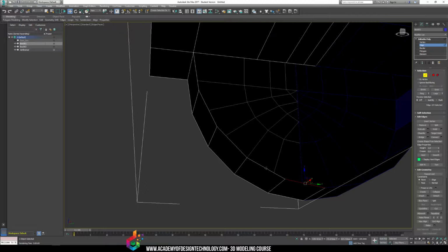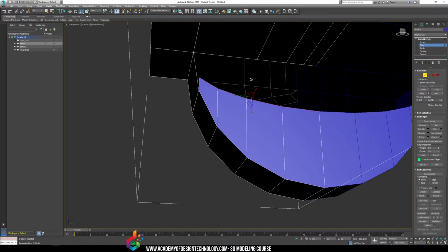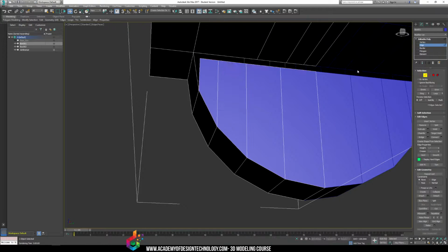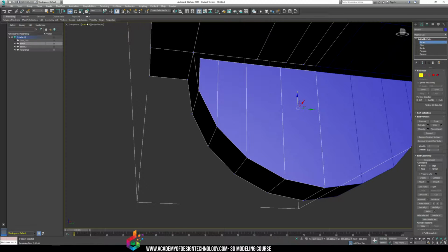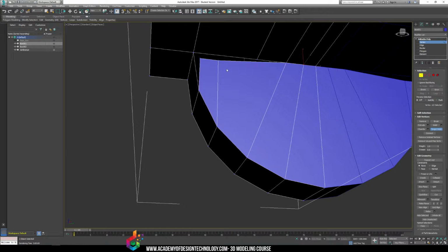Now, normally if I want polygons to meet up with each other, I count how many polys there are, 1, 2, 3, 4, and I'll extrude 1, 2, 3, 4. So grab 4. And then I will flatten them out using the scale tool. Excuse me, drag them up like that. And I will go to vertex mode, vertices, target weld. 1. Oops, my apologies, wrong one. Vertices, target weld, 1, 2, 3, 4.